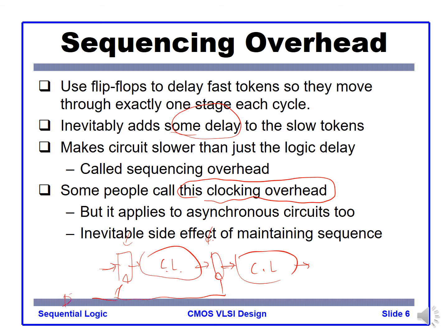If we have hundreds of thousands of flip-flops on the clock, we also need to add large buffers between them, so that we can drive the many flip-flops at the same time. So this is quite a large overhead. Almost 30% of the overall power consumption comes out of the clock tree buffer power.